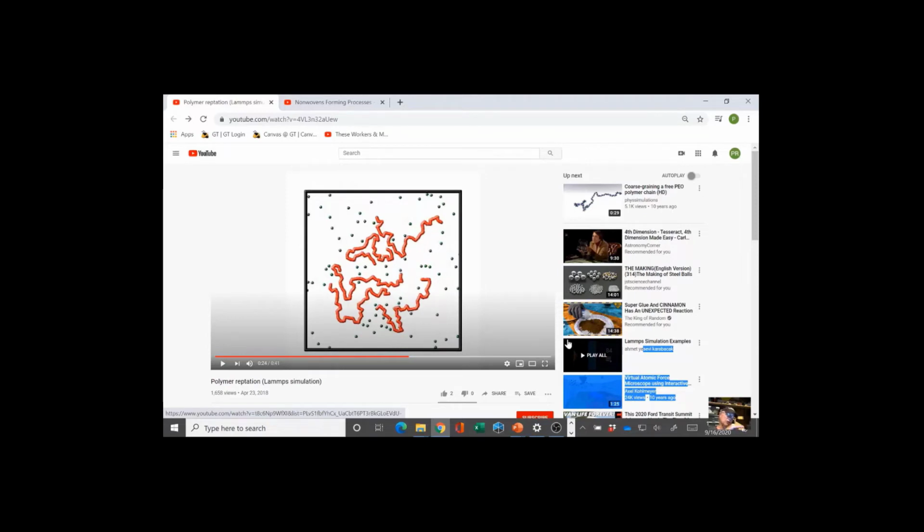And so you saw that as they were making that geomembrane, they were heating it and melting it, getting it above, of course, the glass transition temperature. It was always above the glass transition temperature. And they got it above the crystal melting transition temperature too, long enough that the chains could interpenetrate like that, and cure the seam, and go and seal that seam up, and then they let it cool back down. The crystals reform. The chain motion basically stops. And you now have, as though you had removed the seam.